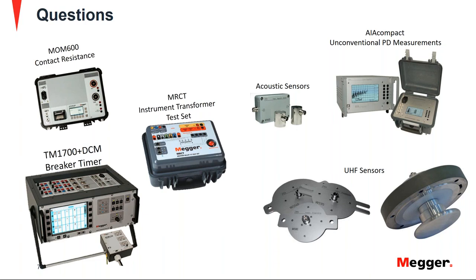But I wouldn't say one's more accurate than the other. The only thing that online monitoring would give you is the ability to monitor continuously the partial discharge activity and set thresholds and alarms and such, whereas periodic online would allow for the ability to come in and do the testing periodically, but there's not really one more accurate than the other at that point. They're both online testing. The only difference is one would be periodic, one would be continuous.